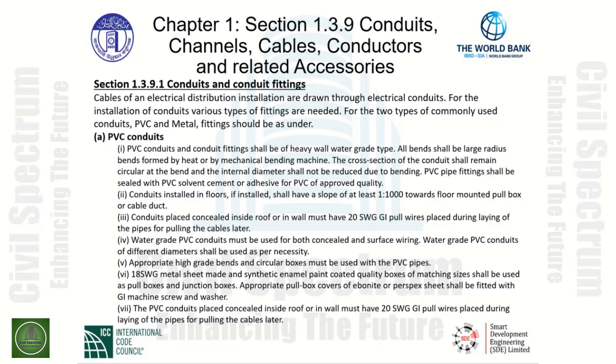Item number 4, water grade PVC conduits must be used for both concealed and surface wiring. Water grade PVC conduits of different diameters shall be used as per necessity. This makes it important that we use water grade PVC conduits for both concealed and surface wiring. Item number 5, appropriate high grade bends and circular boxes must be used with PVC pipes.